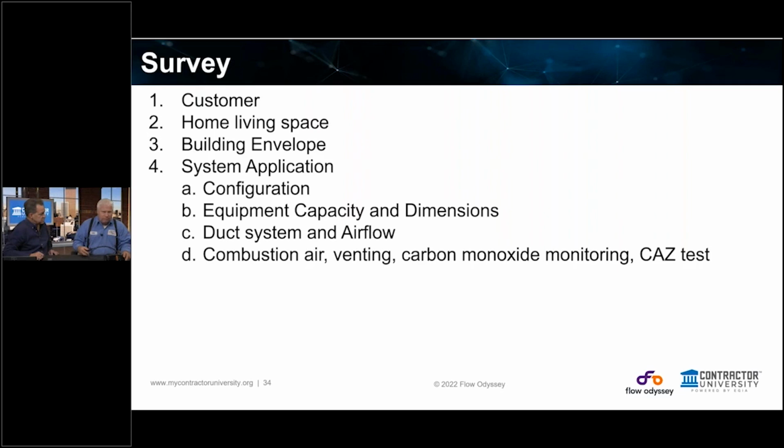And there's a lot of them on the market. What do you do with this? I put the rod into the flue, and I test the flue gas. I'm testing for oxygen, carbon monoxide, and temperature. And if the temperature isn't high enough at the outlet of the flue, I know it's not going to be high enough at the top of the flue if it's atmospheric. Yeah. Especially if you put in something that's 40, 60, 70, 80% efficient, like a 70% efficient furnace, and you put less heat into the chimney, it's definitely not going to work, right? And on the new hot water heaters, the pilot light is literally 1/8 of an inch tall.